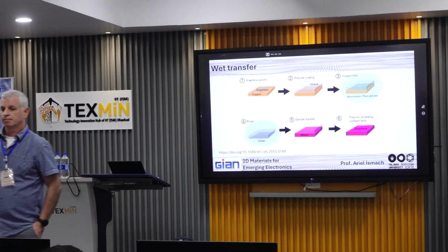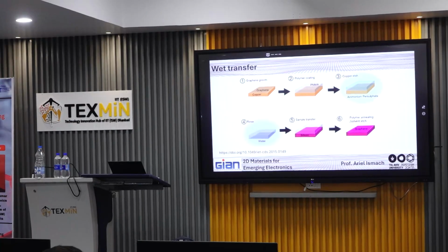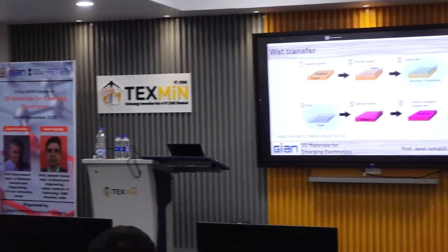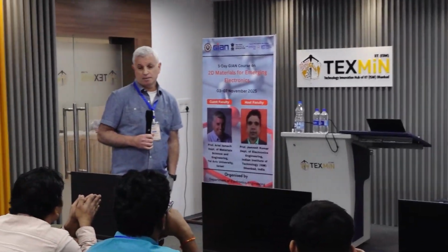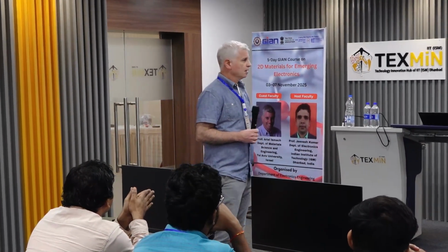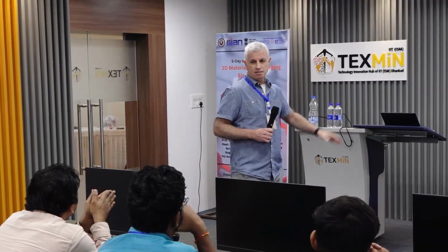What is the best method for coating? The easiest method is spin coating. Is it sufficient, or do you need something very controllable? You don't need a controllable film. The PMMA here is only for support. You're very flexible.